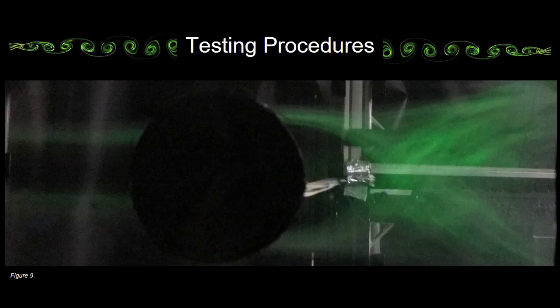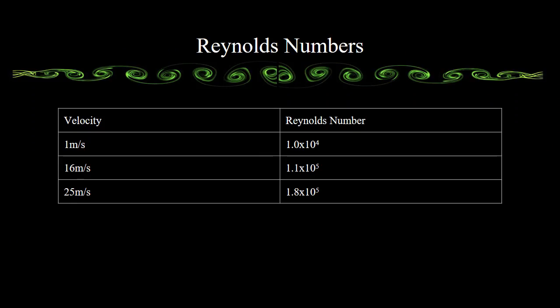In order to achieve surface roughness for aerodynamic appeal, we had someone place the tripping wire at 45 degrees from the horizontal of the cylinder and repeated the same procedures as before. Each group member kept their positions and LabVIEW continued to be analyzed with MATLAB for each test, which allowed new numerical data that represented the rough surface of a cylinder to be visualized and gathered for comparative analysis with the smooth surface.